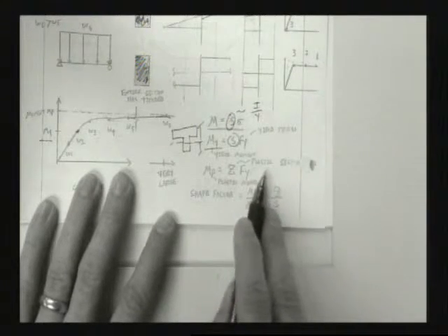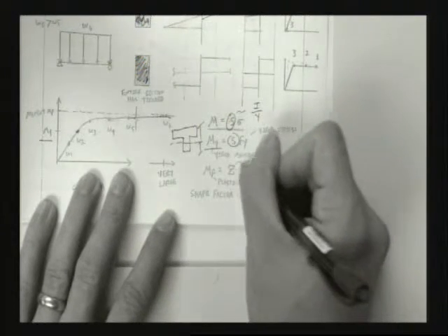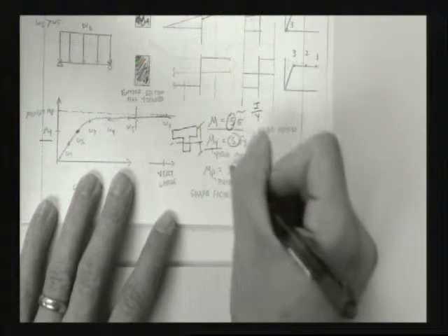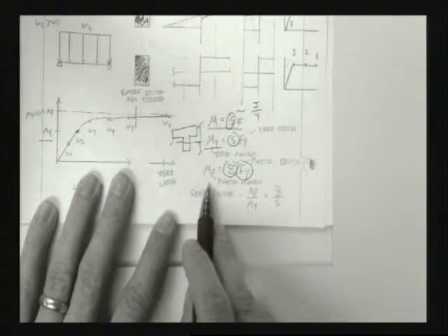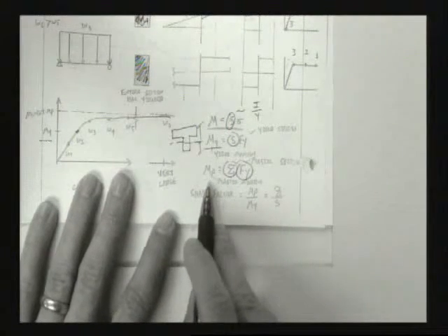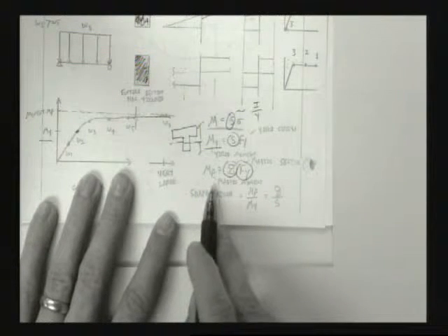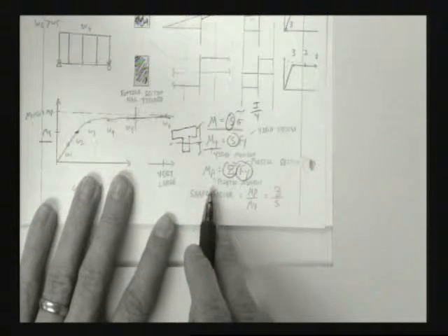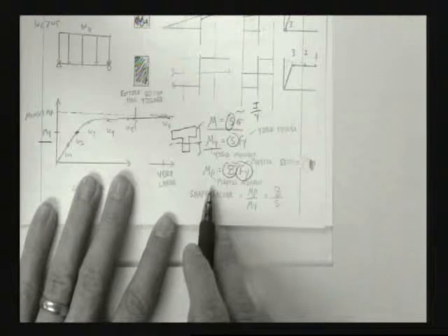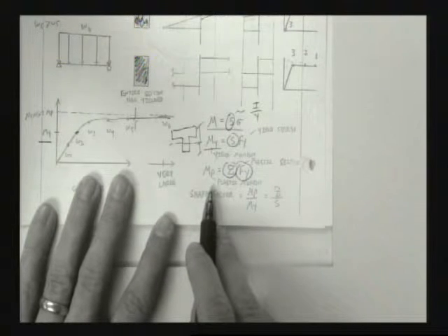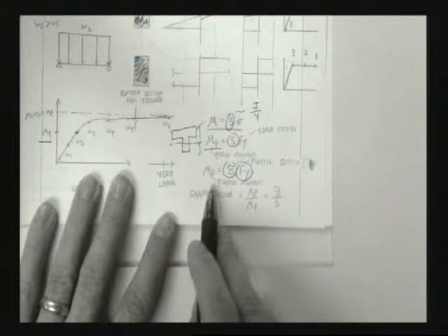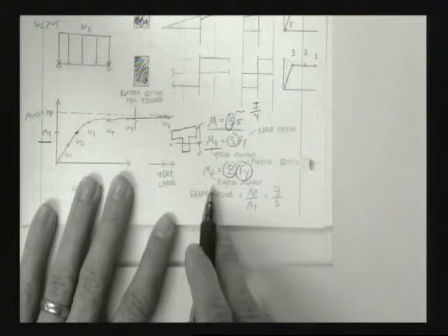And the definition of Z is you take Fy, you multiply it by Z, and you get M sub P. And the great thing is in the past, you've always had Z's given to you in the manual, right? And if you had me for an undergraduate class, I made you calculate Z's. You're going to have to do it again. And now we're going to learn how to do it if there's not a uniform yield on the cross section. Okay? That changes things a little bit.